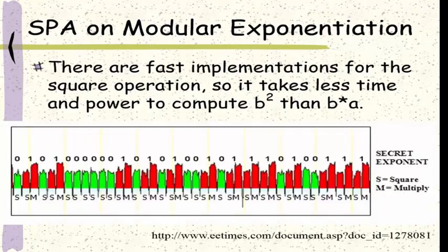From this simplified power trace, we can distinguish the square and multiply operations. The x-axis is time, and the y-axis can be seen as either the power or delay. Square is short, and the tall bars are multiplication. Now recall that multiplication is only executed when the key value is 1. We can easily retrieve the key value from this trace.